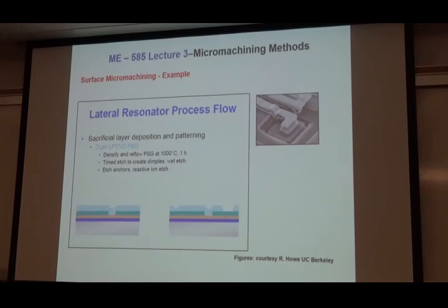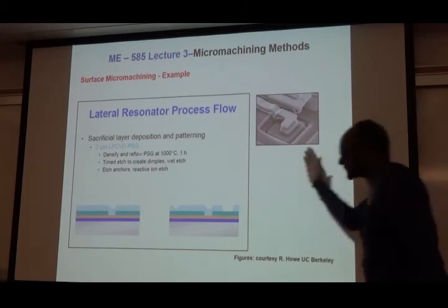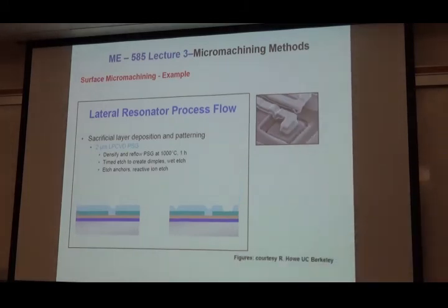There is no theory. The theoretical basis is okay. I could do 1 micron of silicon dioxide, or 1 micron of nitride. But typically it works better with half a micron of oxide and another of nitride there. Okay, good questions. Now, once I have this, what do you think is the next layer?